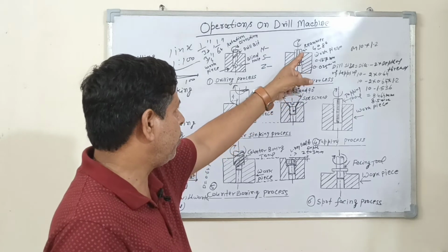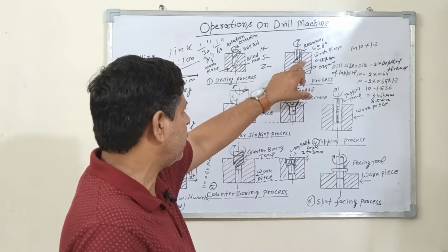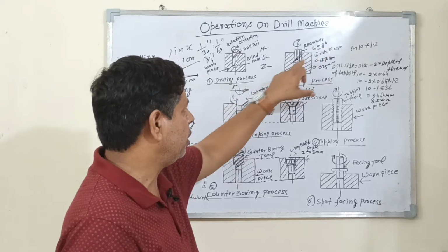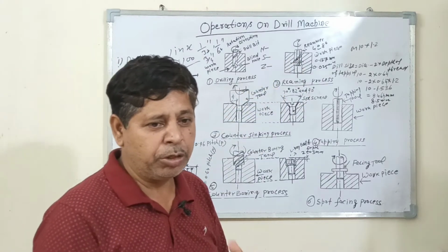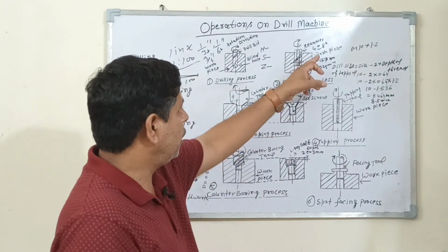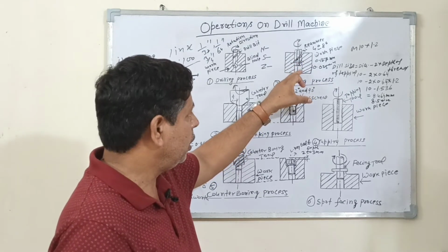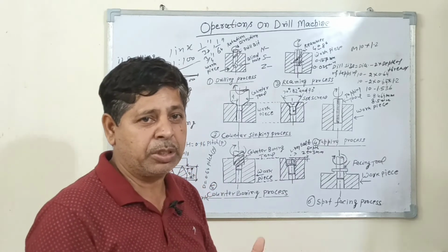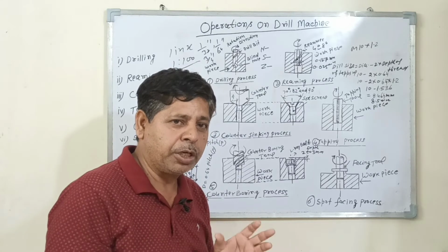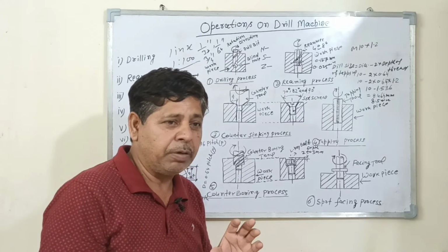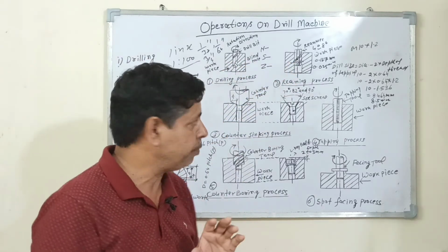The second is the helical type, where the helix angle reamer is used. You will take the angle 4 to 8 degree. The adjustable reamer is used if you want to increase the inner diameter of the drilled hole; then you use adjustable or expansion type reamers. Reamers also come under the category of multi-point cutting tools. The material for drills and reamers is the same, high speed steel.